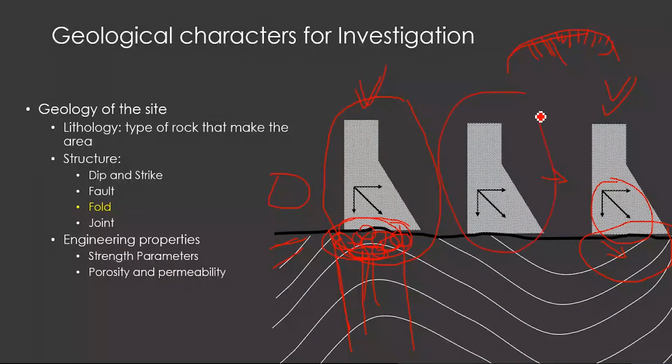But in this case, the condition can be intermediate, because here the dam is located in the limb portion, but the only trouble is the downward dipping strata. So if you do proper grouting and proper locking of the strata, and make sure that there is no movement across those bedding planes, then that situation can be considered as a safer situation for the construction. Similarly, the joints also have the same effects on the construction of a dam.